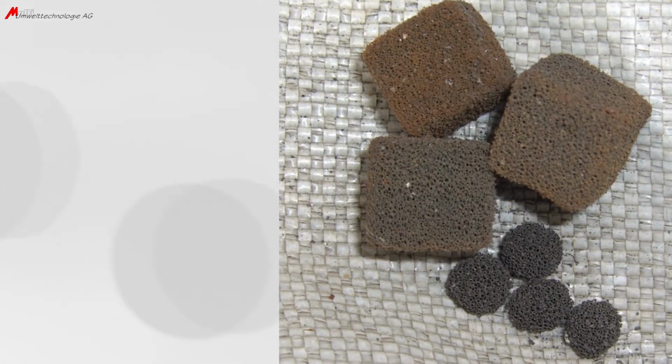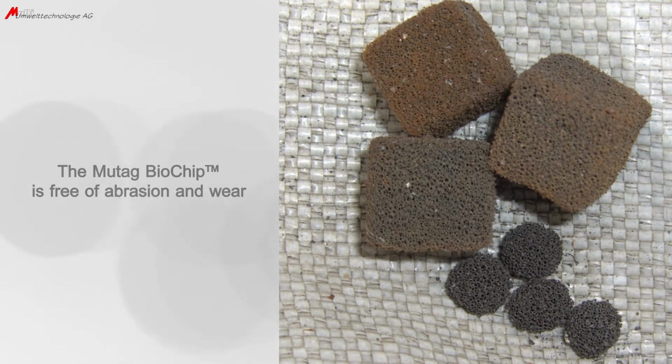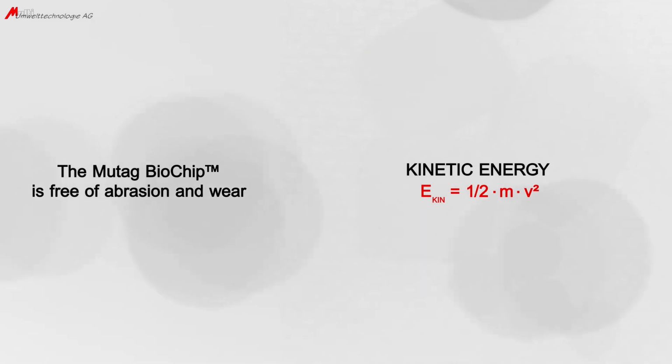These pictures present breakage and abrasion. The abrasion is caused by the high kinetic energy which affects the carriers in the moving bed once they are colliding with the tank walls or once they chip off and abrade each other at high filling rates when colliding. On the contrary, there is no wear or abrasion on the Mutag BioChip. Therefore, no maintenance, exchange or replacement is required due to the very low mass compared to its size.